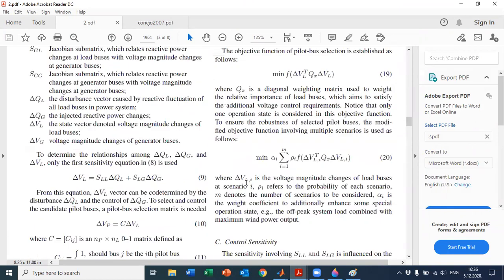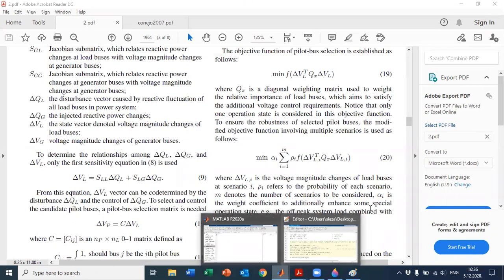So what I've done is I've just created 3 single-phase systems, one corresponding with phase A, one with phase B, and the third one with phase C. For each one of those systems, we determine the PV generation, the control nodes, and the pilot nodes. And then when we merge this code with the code we've done earlier, we are going to just say that phase A has these control points and these pilot points, and it's the same for phases B and C.